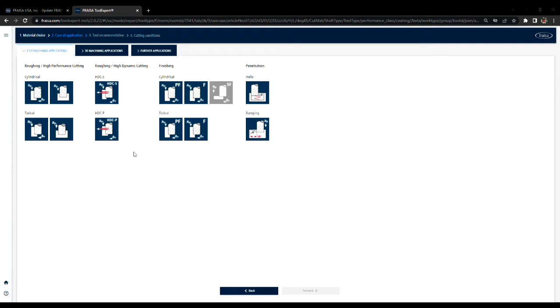So the idea is to choose the setting that best fits your machine type. So for instance, a speed setting might set you at 400 inches per minute, and certain machines will definitely not hit that everywhere. So it would make more sense to choose the performance setting, lower your feed rate some, and increase your radial step over to match the same metal removal rate.